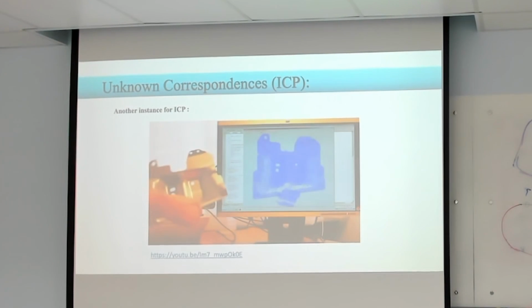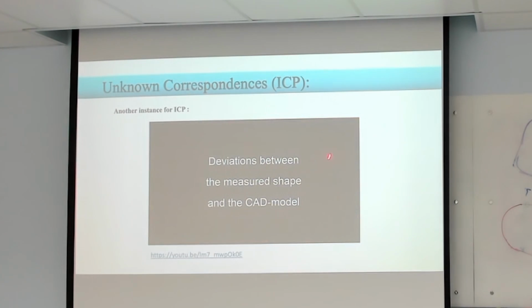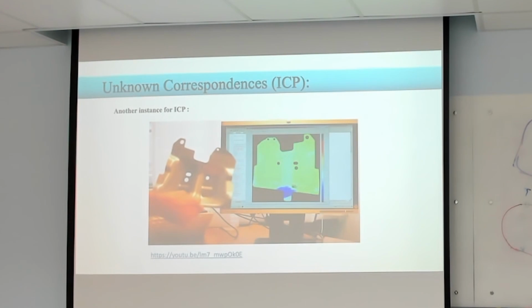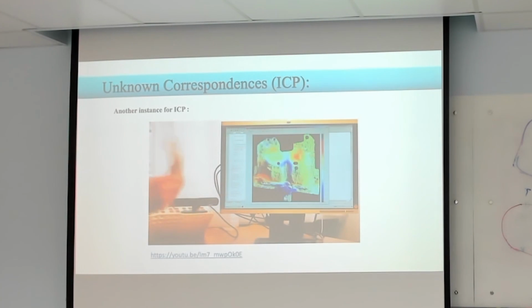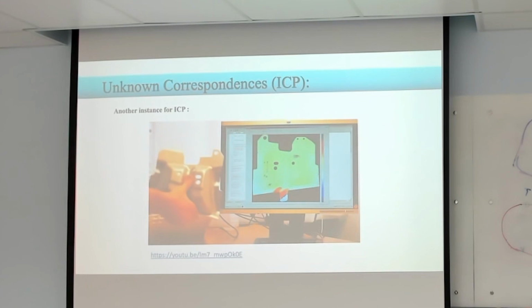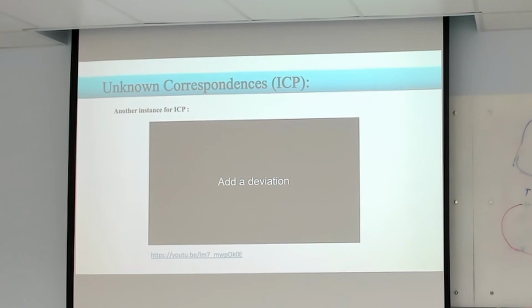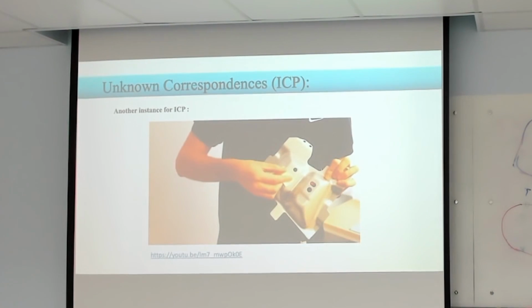Then with ICP matching, you can see that when it shows it again, it matches to the map that it has already. You see, this is the general map, and this newly scanned data will be plotted and mapped on the previously known one with the same idea. And here you can see another representation of the same idea. Even with the rotation, you see that the constructed map is the same. It's performing the algorithm perfectly.